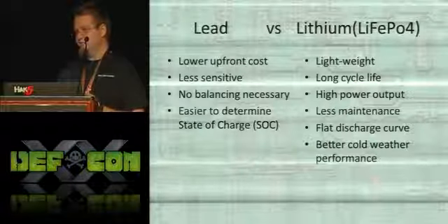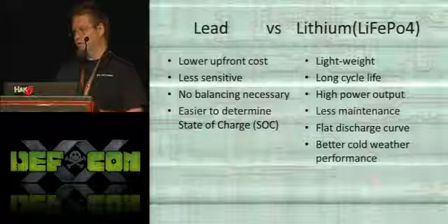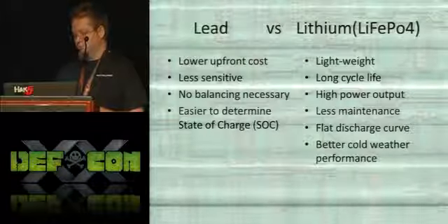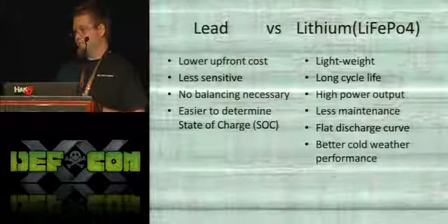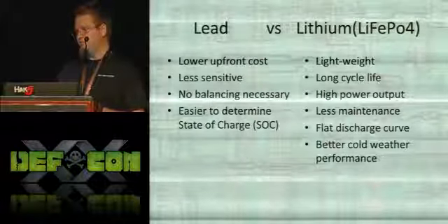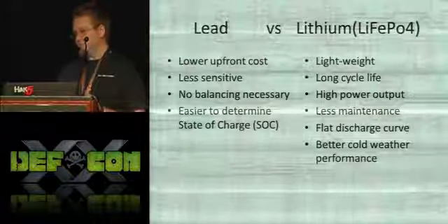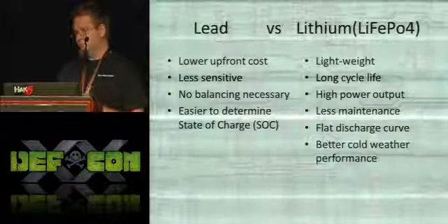Lead-acid batteries, because they gas at the end of the charging cycle, you have to put water in them every few months to not kill them. Also, cold weather performance, lithium's a lot better at this. A lead battery will lose half its capacity when it's too cold out, and lithium will only lose about 10 or 15%. And if you heat them properly, then it's not really an issue.